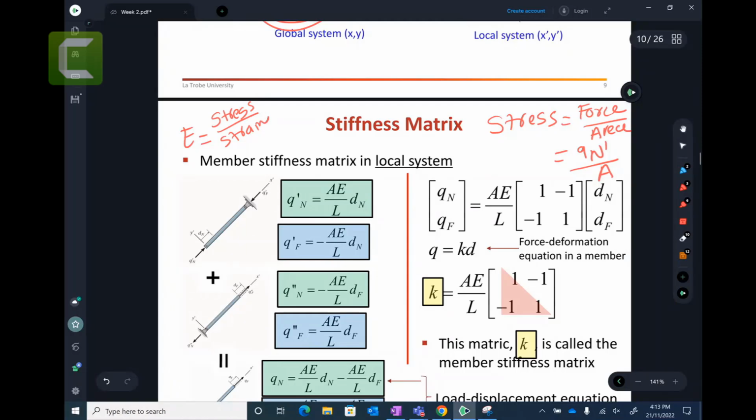That is the definition. So if you take the ratio of stress over strain, again, you don't need to remember these equations. We're not going to ask you in the exams to prove these ones. No, you don't need to remember anything. It's just the logic. I want to make you familiar with all of these. So if I want to calculate the stress, I can substitute here. So stress is equal to Young modulus times strain.